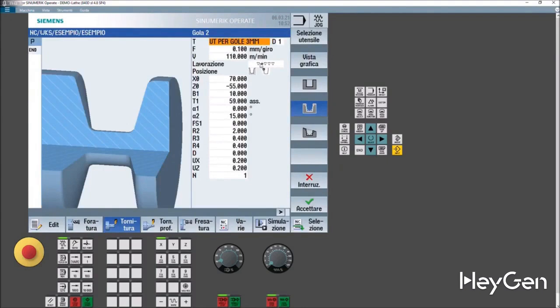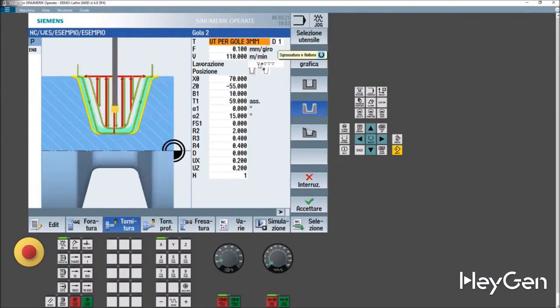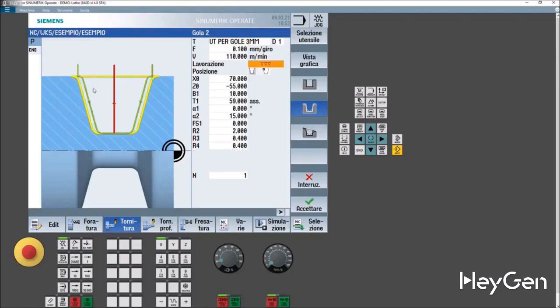To work on our groove processing, you can see that the groove is already inserted. It's done. More roughing though. You can also just rough it out, or just finish it. So it enters, lifts, moves, and goes back in. Or you can rough it out and finish it normally. With the groove tools, you rough and finish X0.